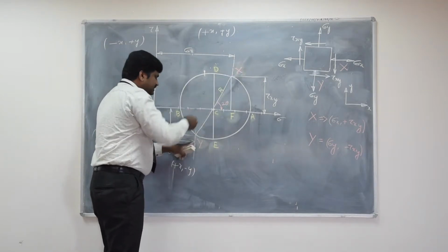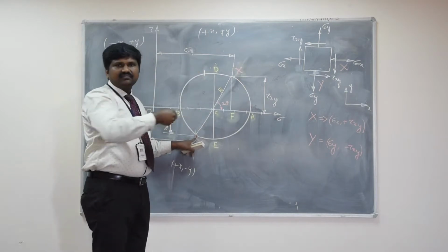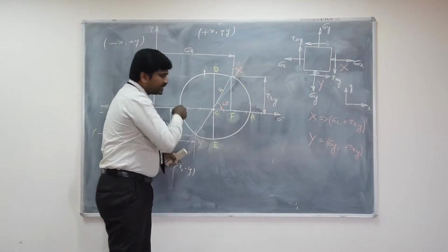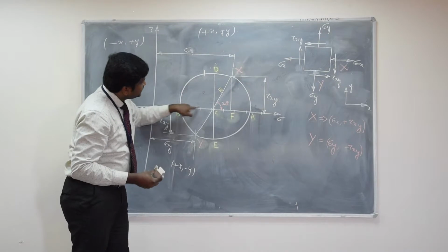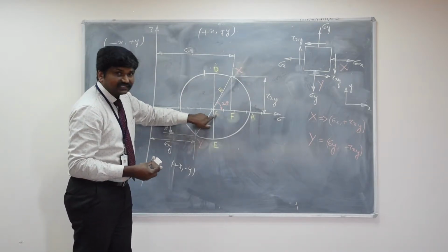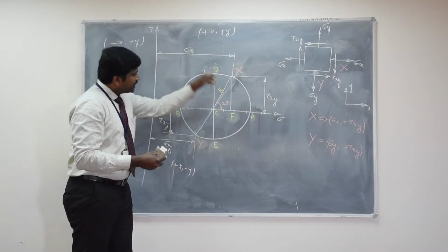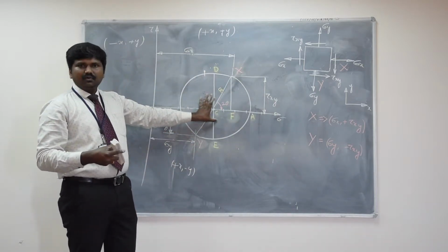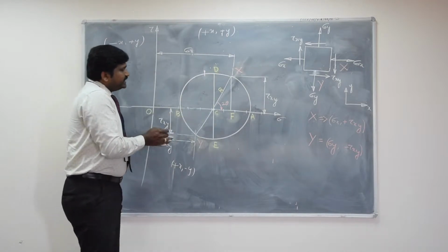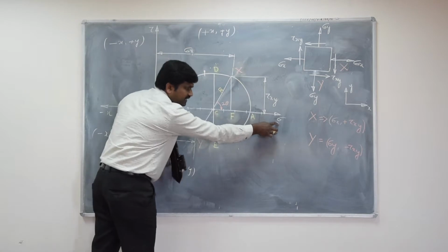So actually the xy line is the diameter of a Mohr circle. This xy diameter will intersect with the x-axis at point C. Now, taking point C as center and CX as radius, you draw the circle. After drawing the circle, what you get is a Mohr circle. Now the intersection of this Mohr circle with the x-axis, that is the sigma axis, is important.